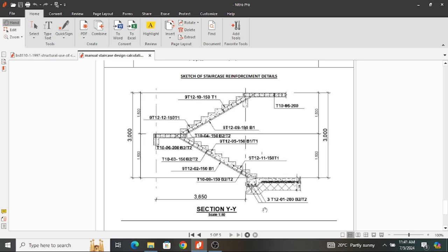Sometimes at this starting point, it could be starting inside a beam. Therefore, the reinforcement at that section is governed by where it is starting. So you have to get the total loading, you get the loading it is exerting on that beam, and distribute it there and find the reinforcement that is sufficient to be carried by the beam.